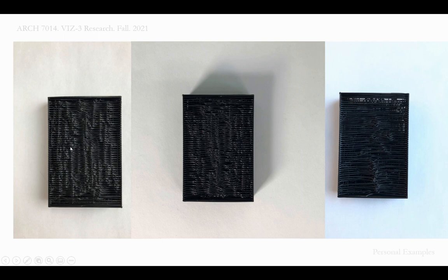And also with this box, something that I did different is I added a plane to the top that I extracted all the points from, and then I had the machine run over each. I had the machine run over the top really, really slow, which again is something that we can manipulate in the F function that I showed you in Grasshopper.